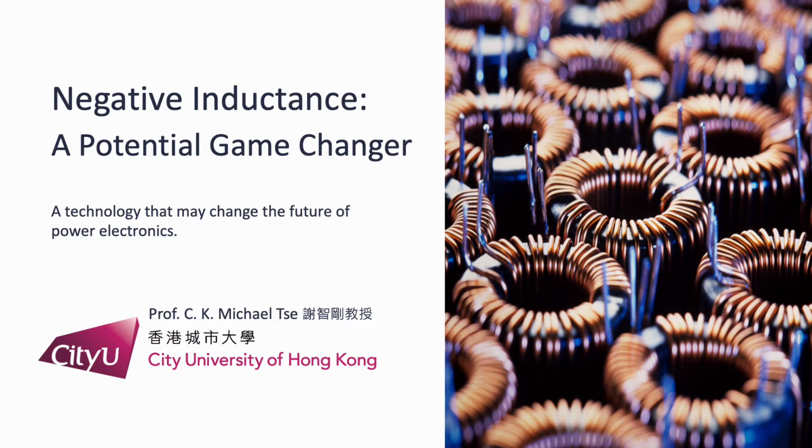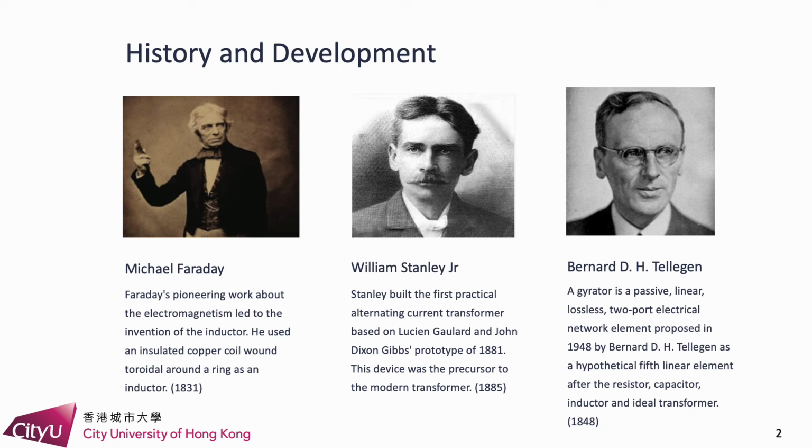The topic of my talk today is inductance, which could be very familiar to many of you here, but at the same time, the concept of negative inductance could be totally unfamiliar to many of you. So in this talk, I'll explain the key concepts of negative reactance and how we achieve the synthesis of negative reactance. And hopefully the presentation will be interesting to you. Let me start with a bit of history.